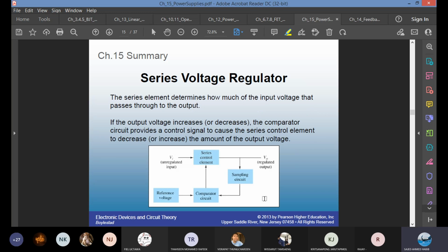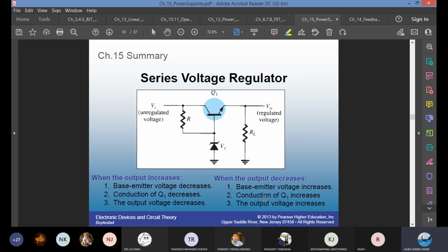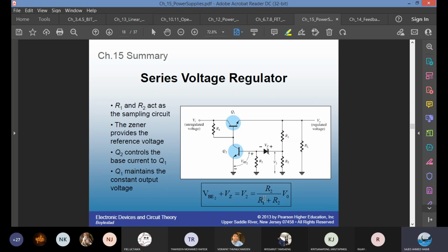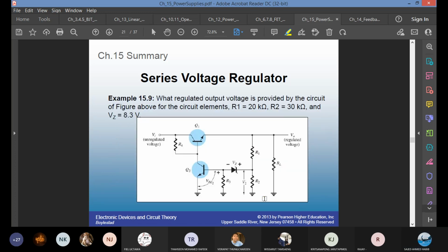We had some series discrete elements to create voltage regulator. I asked one of these type of questions in the quiz, maybe also important for the exam. So review these concepts again. In this case, V out is Vz minus VBE. Another case, you have Zener with 2 transistors.